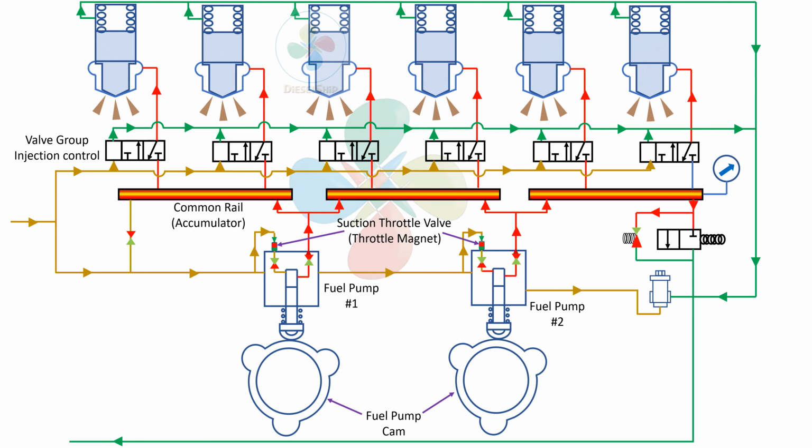And then, how does it terminate the injection? The valve group simply opens the drain port. So the fuel immediately drains, meaning the fuel from the injector all the way to the block is completely drained, right? So this also does that function. And the final function is, if anything happens to the injection components, say a large leak, and the emergency shutdown has to be activated, the first thing that gets the command in this electronic injection is this valve group. This valve group immediately shuts to the position that you see here. Right now, what you see is a completely shut position. So this has to happen.